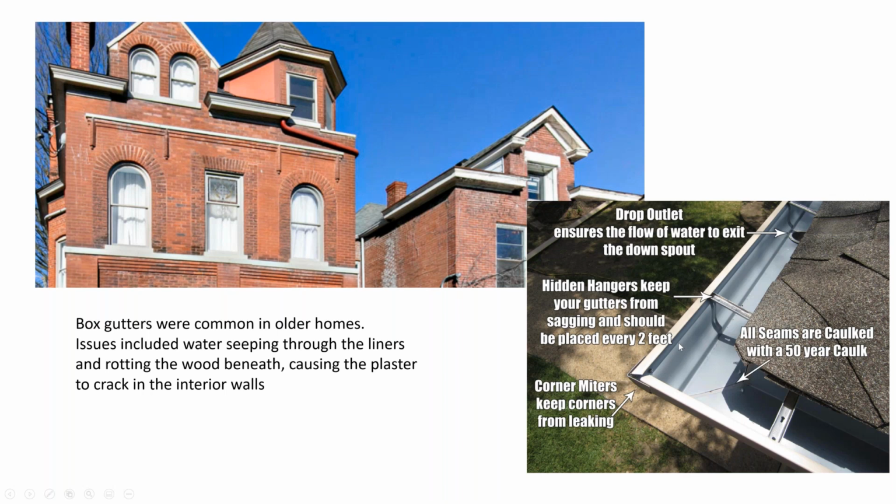However, it's really interesting to note that if ice builds up in here, and this is why it's so important to keep your gutters clean. It's going to come up on your home inspection report all the time that the gutters are dirty, and people think nothing of it. It's really important. You have leaves in here and you stop up that drain, that downspout, and then it freezes, the water will get up underneath the shingle and drip down into the foundation or into the wall.